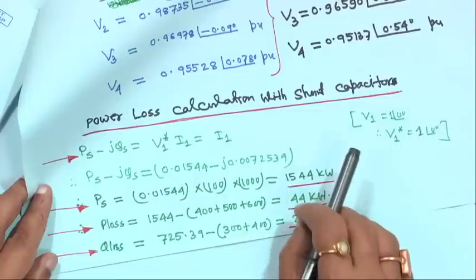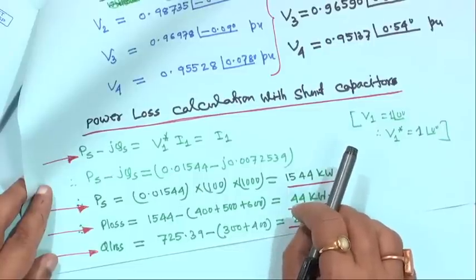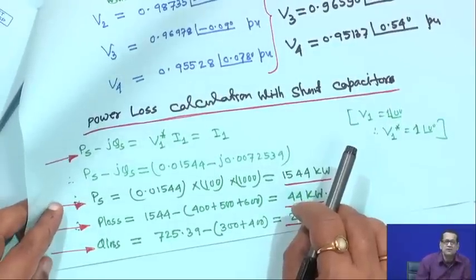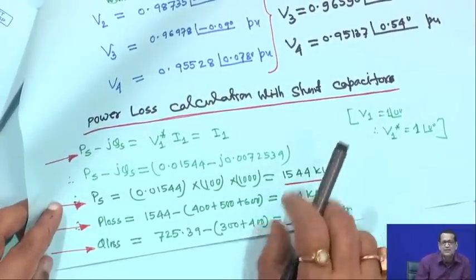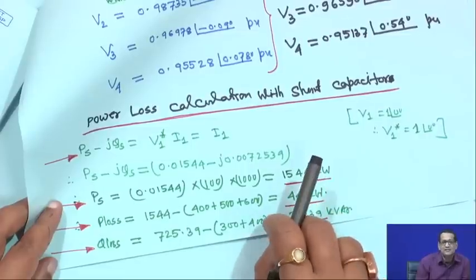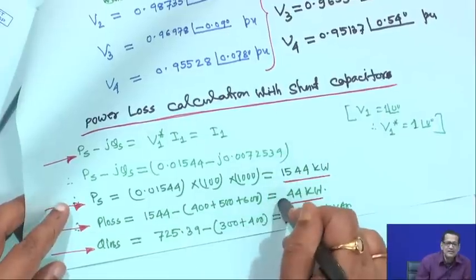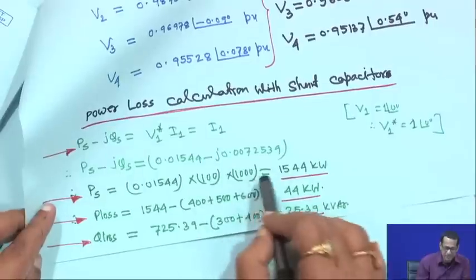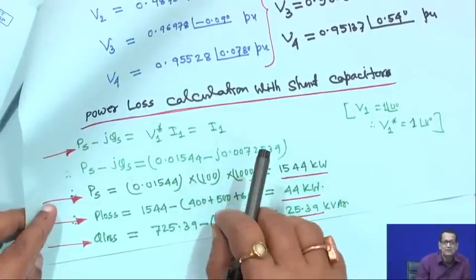Say you have a 120 node distribution network or even a larger one, there you cannot put shunt capacitors arbitrarily, then instead of gaining you will be the loser, loss may increase, because you put it in a non-optimal place. In the classroom exercise I cannot teach you that optimality, but I will tell you at the end of all these things how one can do the optimal thing.